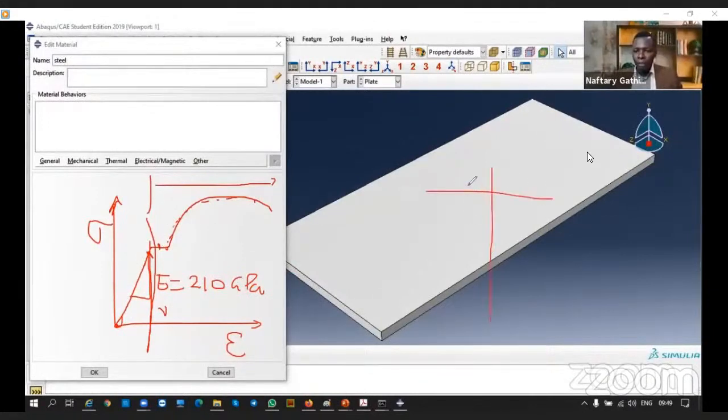From the experiment, you are going to have stress and strain. So from 0, 0, of course, it's at the beginning. At this point, let's say at 350, that's my yielding. Maybe the strain is 0.2%, or 0.002. Of course, you don't write in percentages. Then maybe this is the yield plateau here, so still at 350, I can have the elongation coming to 0.8%.